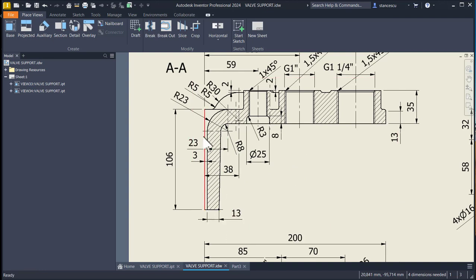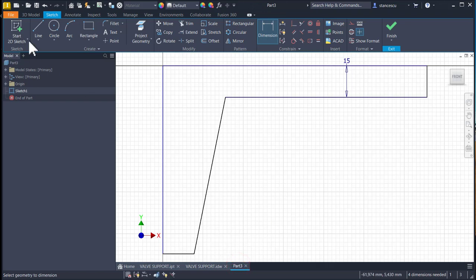We have this face 3 millimeters from this face to this face, parallel the two. 23 is the distance to this center, and the radius is 8. So we'll apply 23 plus 3 to this center. Yes, and 13 comes from this point is placed at 13 plus 3 from this face. We start with this face, not with this. Okay, fillet radius 8 between these two.